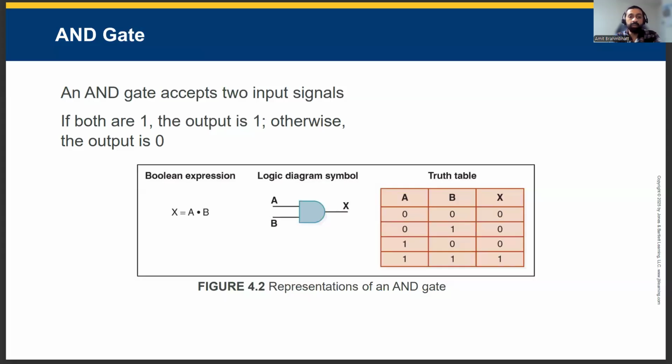The AND gate takes two inputs and outputs 1 only if both are 1. Any 0 on its inputs forces the output to 0. In Boolean algebra, we write this as AB, meaning A and B. Visually, an AND gate is a D-shaped symbol and captures the logical idea of both must be true, which is everywhere, from enabling a write only when a register is selected and a control signal is asserted to combining bit patterns.